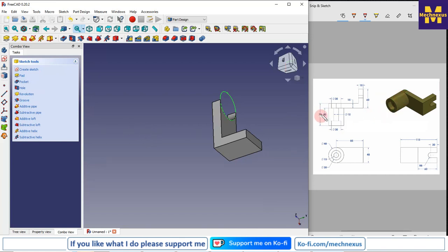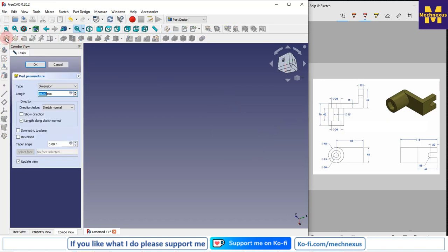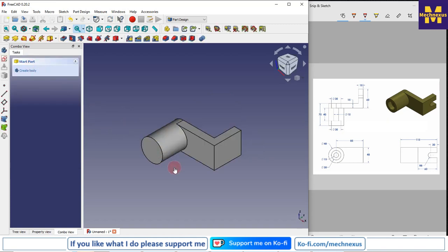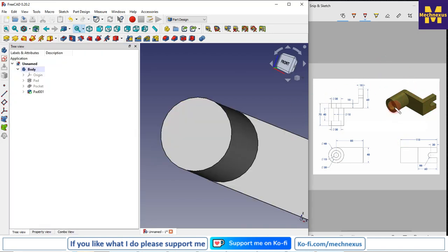Extrusion length is 70. So I will simply select the pad and I will say reverse, and here I will give my direction length 70. Now I will say OK. So we have made the overall shape. Now we will make this counter bore hole.